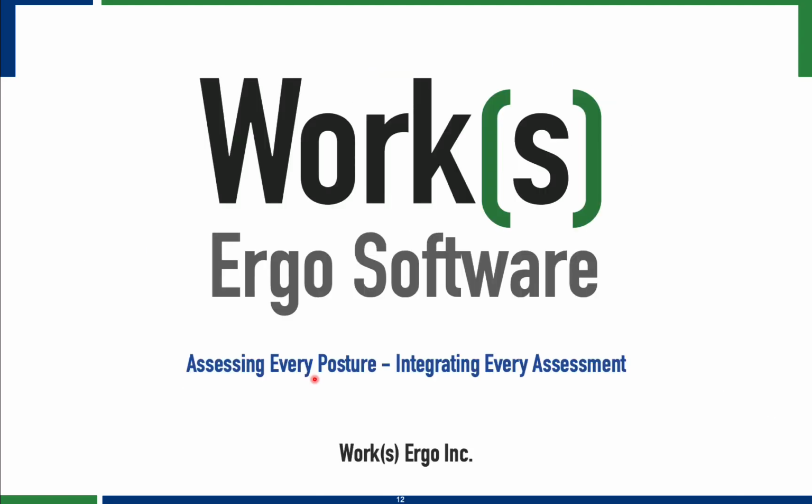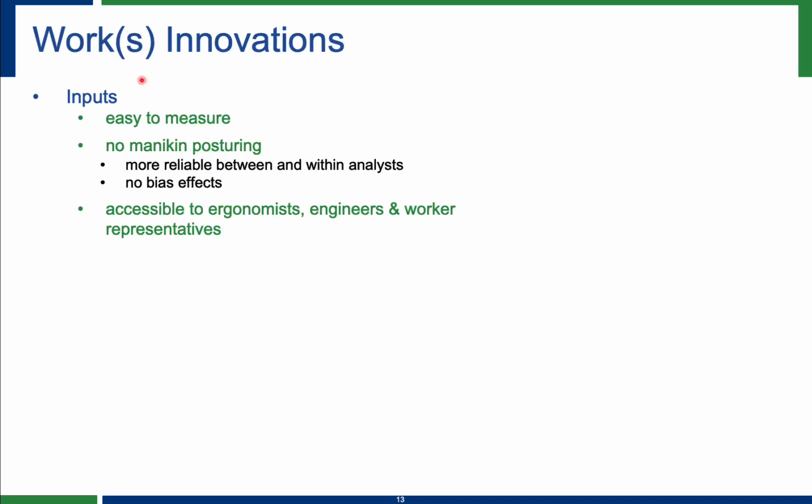So this is where our Works software comes in, and I want to just go through some of the innovations that are associated with it. One is that we try to use only fairly easy to measure variables that most ergonomists have learned. Things like reach and height, things like hand orientation are fairly easy to observe and need to be input. There's no posturing of a mannequin, and so you are essentially allowing the software to pick all the feasible postures, and then we've come up with ways to deal with that variability.